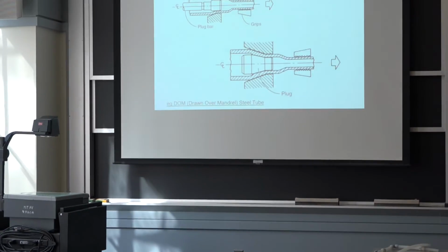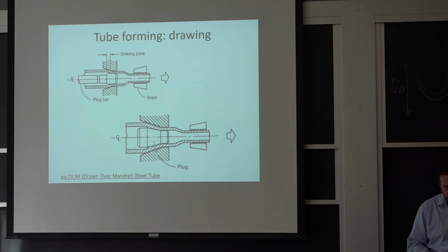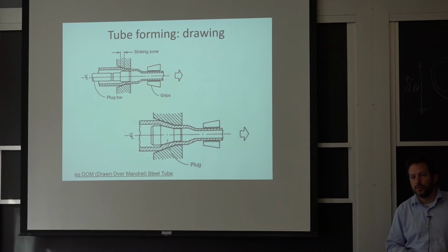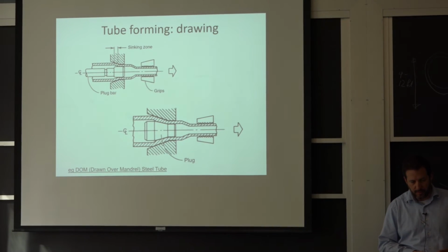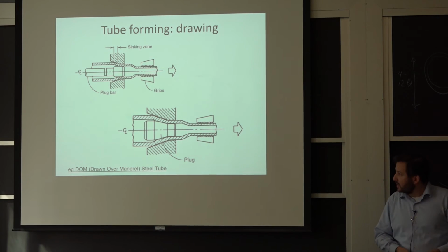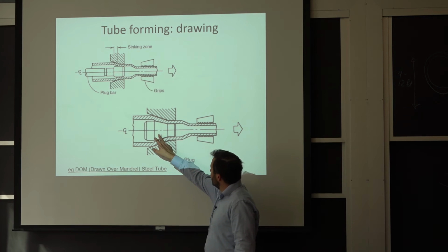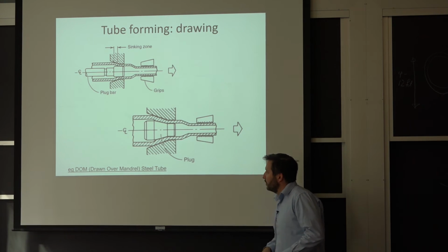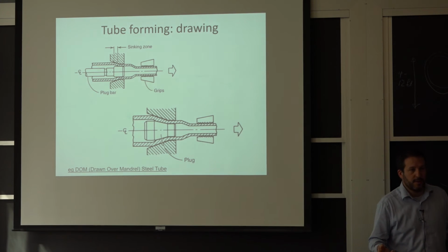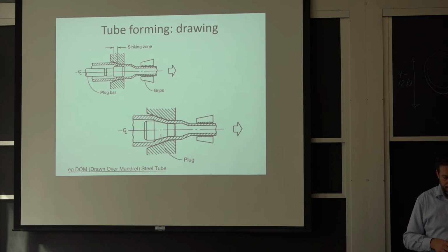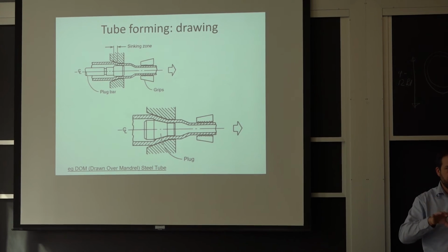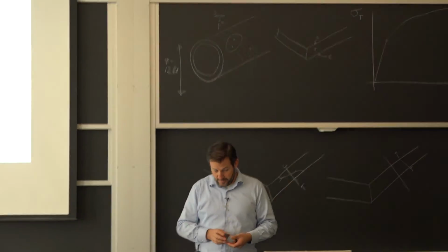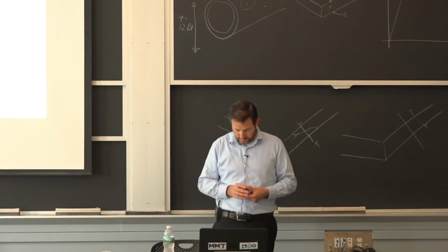Okay, this is good. If you try to make tubing or pipes with a very controlled internal diameter and external diameter is where you'll use drawing a lot. And you can see in this case they have what we call a plug on the inside of the tubing. So you make it approximately to the dimension you want first. And in this last stage, where it's almost to shape, you get your very precise control of the OD and the ID. And a lot of times, that's also increasing a little bit your yield strength,